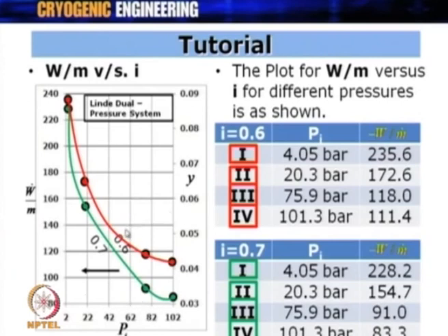This we will have to understand with all the logistics which I am just talking about. What happens to WC1, what happens to WC2. As you go on increasing the intermediate pressure ratio, the pressure ratio for the first compressor increases, but it is subjected to less mass flow rate.